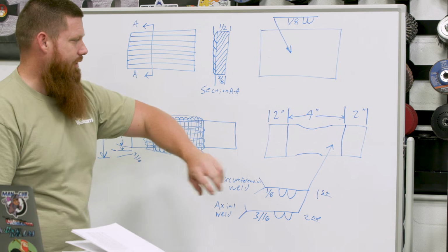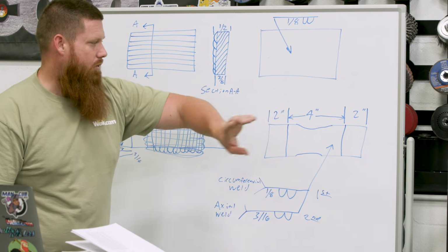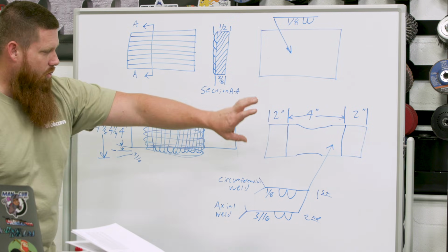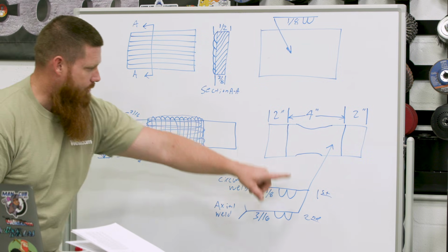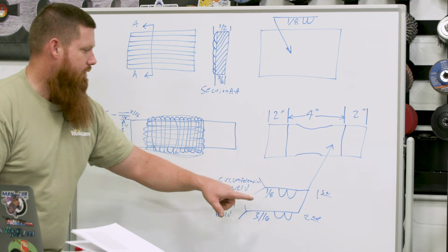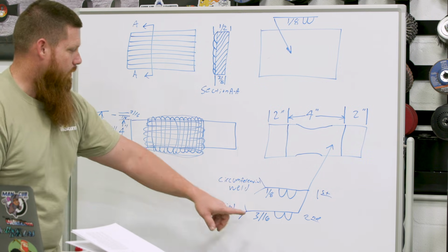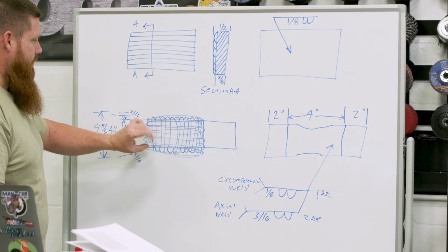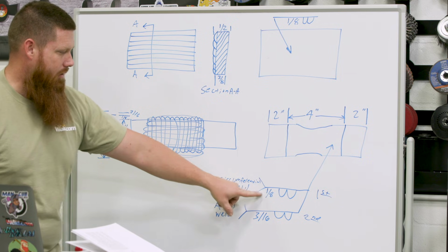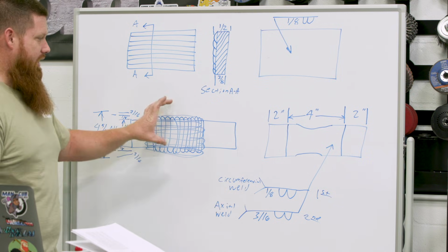Okay, getting back down to the shaft here, we have this piece overall 8 inches total, but it's worn out in the middle. So our first step is a 1/8 circumferential weld of surfacing welds. And then our next step is 3/16 padding of circumferential welds. And that's just going to expand my diameter basically twice that weld size once I'm done.